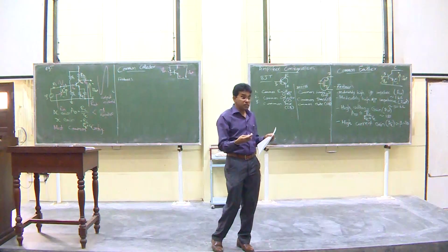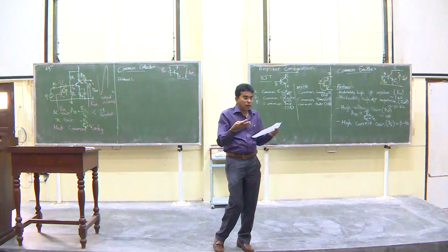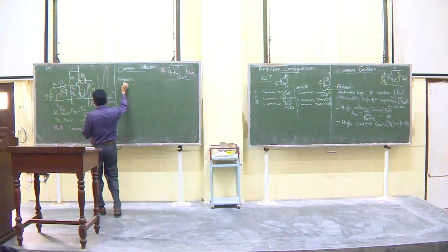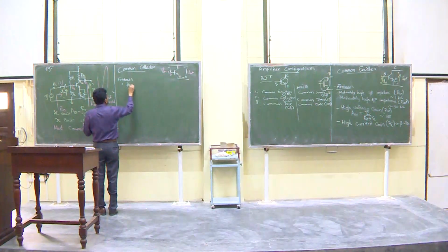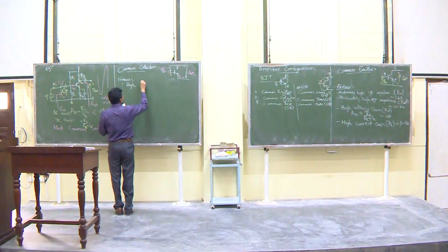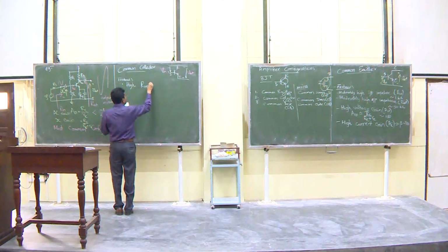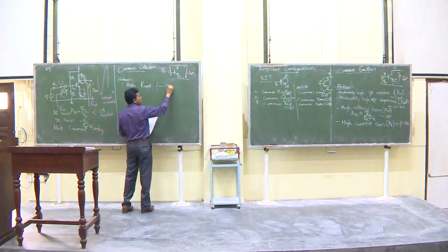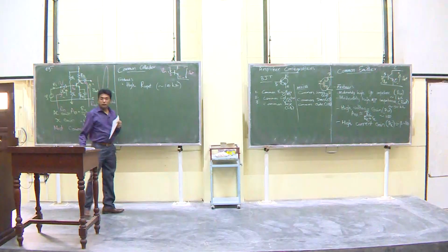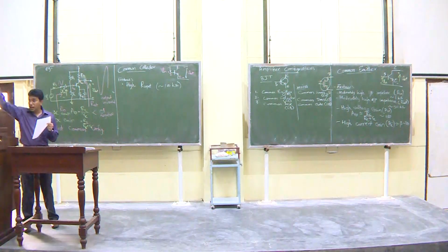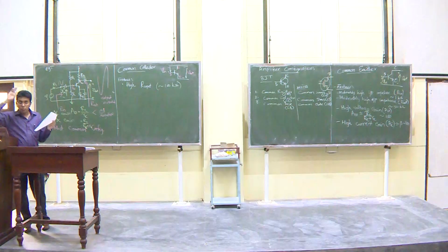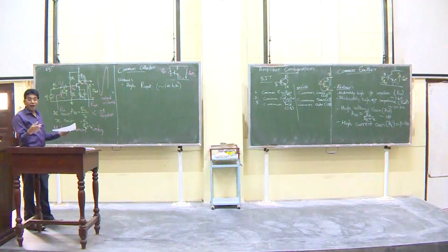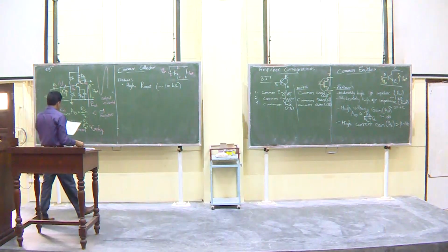So, therefore, input impedance is rather high, high Rin, in the range of 100K, right? Again, this is not very high like 1 mega ohms, but these are BJTs. So, one issue with BJTs is that high is not that very high, right?